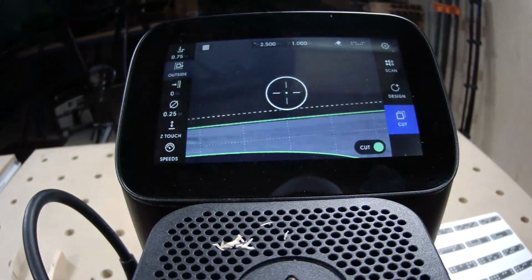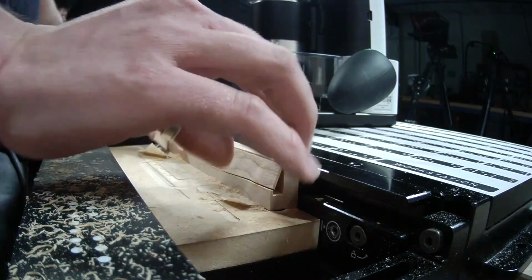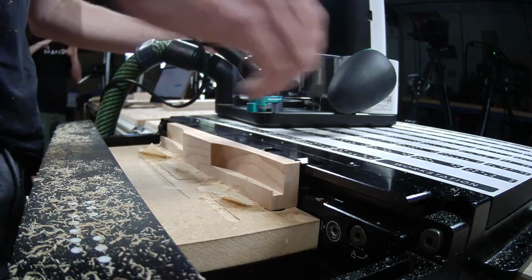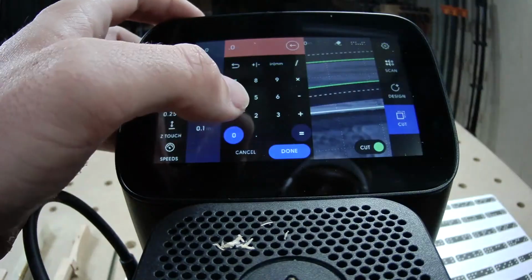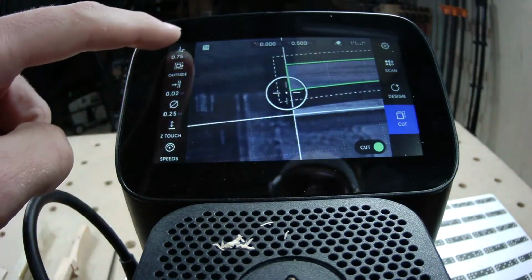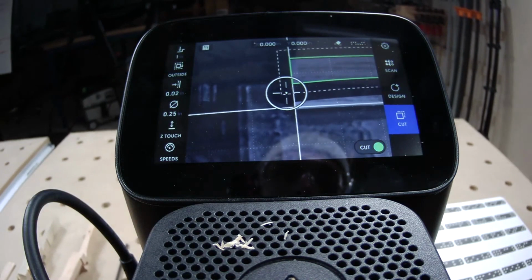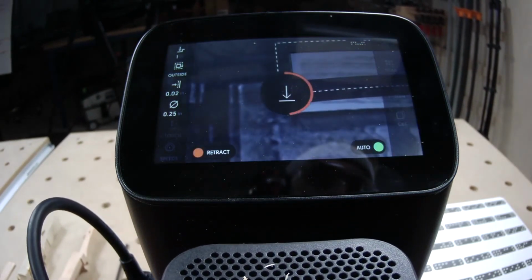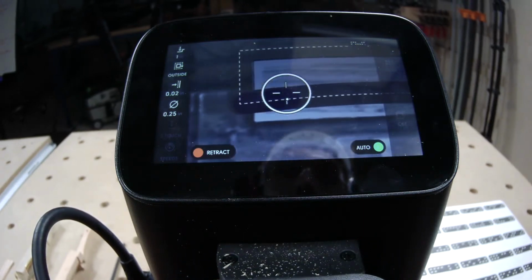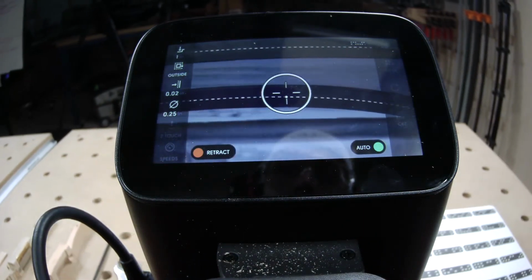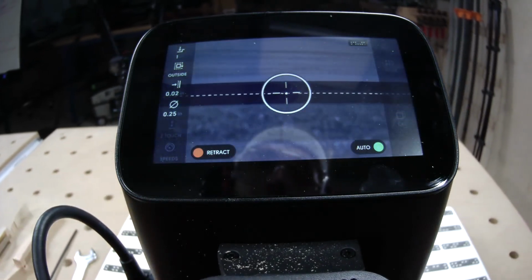In fact, if you're not interested in creating custom anchors, you can still use all of the files that we've put up on Shaper Hub. So for all the hardware files, for that star file, that sort of thing, for instance, I've gone through and added custom anchors to them so that you don't have to think about any of this. You just grab the file and it's got appropriate options for you to place with, be it custom anchors, or you can always switch back to the way it was previously with the bounding box, the regular 9 anchor points.